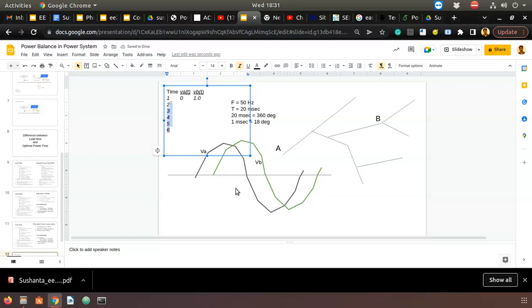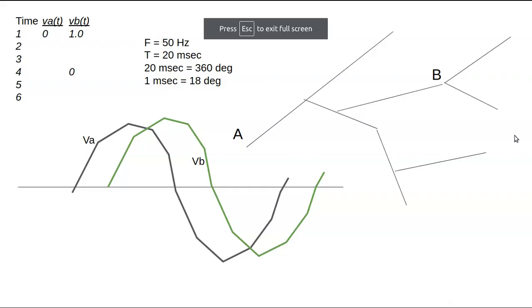You analyze all this data and try to map it on the same time. Wherever you are crossing zero, that can be the starting point. So the zero of VA, and let's say VB achieves zero here. Now you will see the timestamp here and the timestamp here, this zero here and this zero here. The gap between the two zeros will be the phase difference.